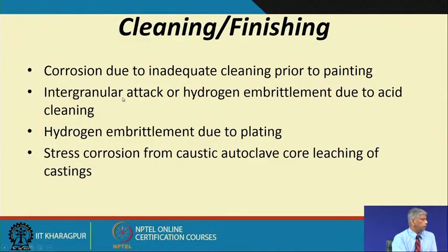And again, in many of the cleaning and finishing operations, corrosion due to inadequate cleaning prior to painting, intergranular attack or hydrogen embrittlement due to acid cleaning, hydrogen embrittlement due to plating, stress corrosion from caustic autoclave. So, this hydrogen embrittlement creates a lot of problems.